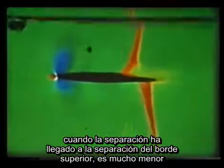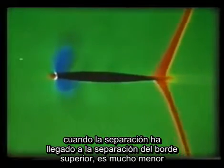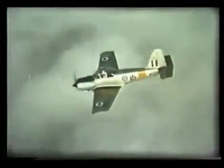But it is flow separation that causes most of the troubles in the earlier part of the transonic range, when the shocks are moving back. Once the shocks have reached the trailing edge, separation is much less. It is flow separation that causes the shock stall, so called because the effects in flight are rather like the normal low speed or high incidence stall, also caused by separation.